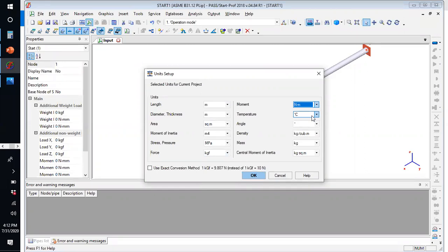So maybe the length you choose is too long. Click on the line in between, double click on it, then shorten the length of the pipe you used. You know, you are working in meters, you shouldn't put 1,000. Since you're in meters, you should put like 10.